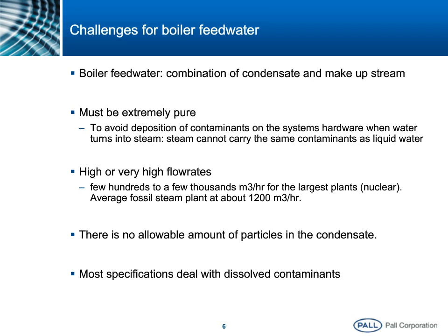The second challenge for boiler feed water or condensate is that we're dealing with high or sometimes very high flow rates, anywhere from a few hundreds to a few thousand cubic meters per hour for some of the largest plants. And in that water, the main specification in terms of solid contamination is that you should not have any.